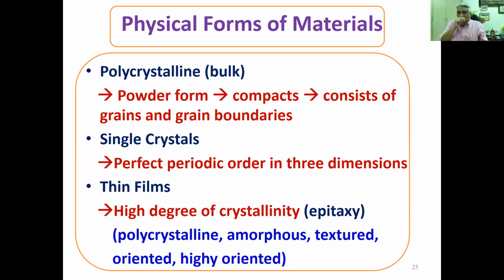In a polycrystalline material, that long range order is not there, but long range order exists to the point where the crystallinity is. That means a grain. I've shown you a picture of, I'll show it again, a grain, another grain. So within a grain, you have single crystalline arrangement of unit cells. That means there's a perfect periodicity within the grain. Grains, if you recall the picture that I showed you yesterday, the sizes vary anywhere from 1 to 50 microns. So within that 1 or 10 or 50 microns, you have perfect periodicity of all these unit cells. But then there's a break in periodicity in the form of a grain boundary. Then on the other side, you have a periodic formation of the unit cells, which you call another grain, right? So you have an ensemble of crystallites. That's why the name polycrystalline is. But here, it's only a single grain.